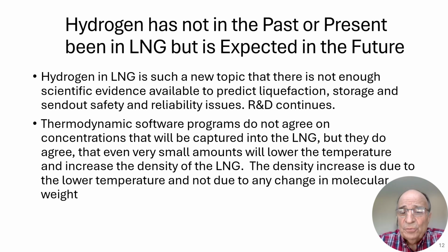Thermodynamic software does predict how hydrogen will behave when making LNG. However, the thermodynamic software is at its limit, because if you use two different thermodynamic software programs, they may not match the same data output. So there's a question about which information is correct. You'll see some data that has been extrapolated from thermodynamic software. You'll see that in further slides.